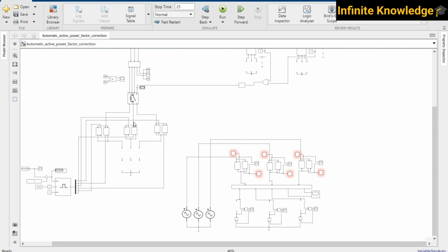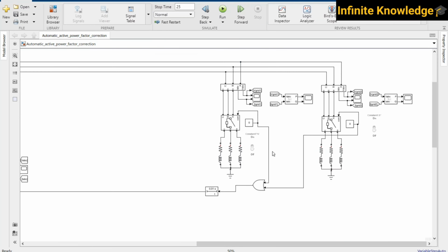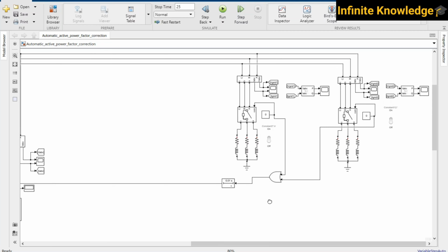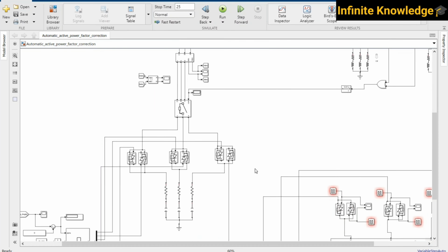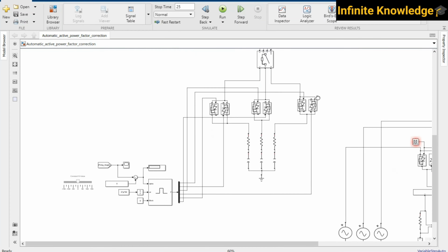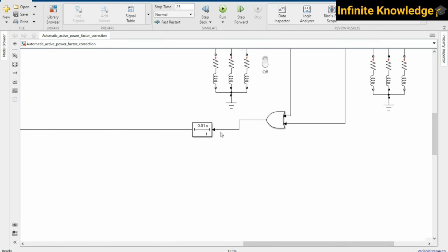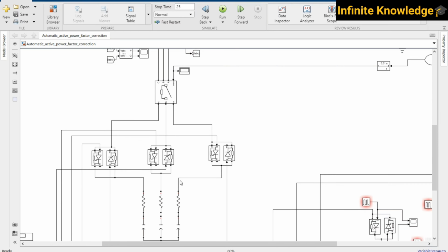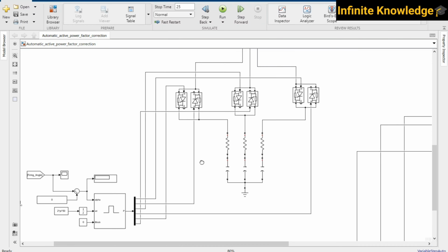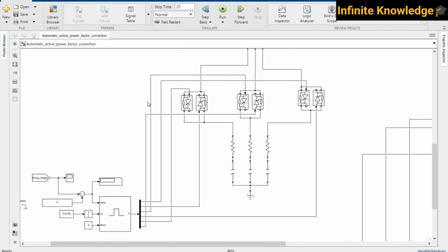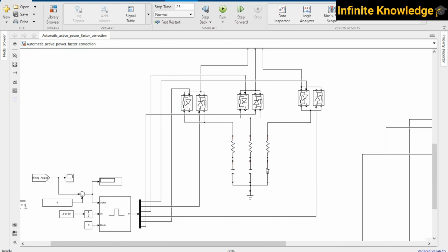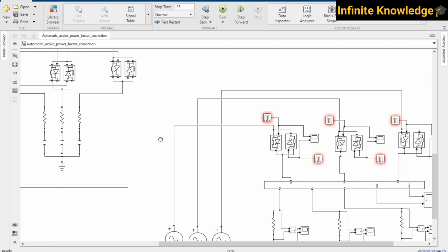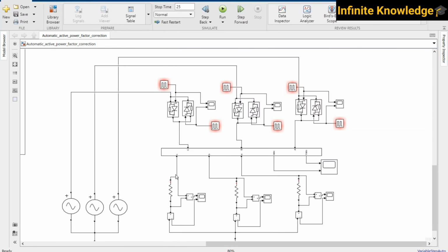But if you comprehensively go through this model, you can see that there are two switches, but no matter what the load is, there is some time delay which I require to avoid turning on and off frequently. If I did not use this delay block, it would continuously switch on and off, which may cause unnecessary switching. You can see this is the firing angle control. This is thyristor based control, and how this thyristor based control works, that example is from this block.